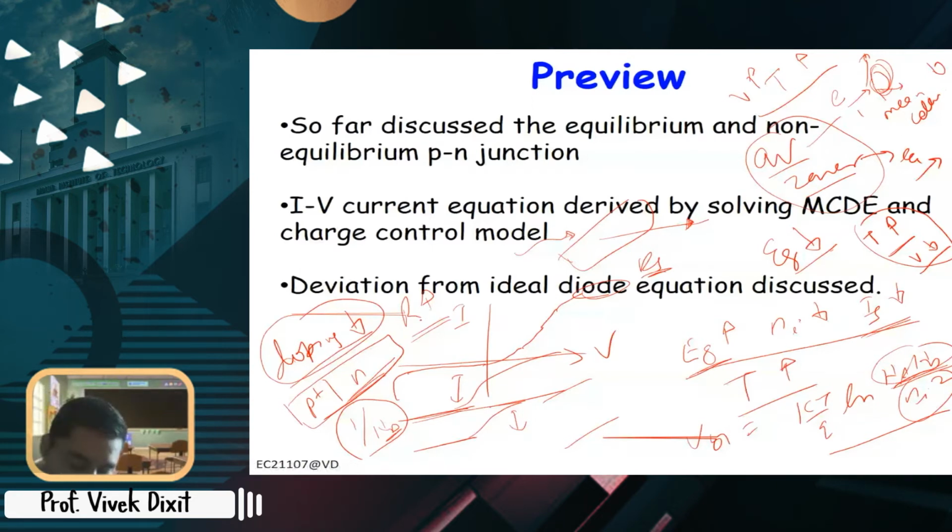So that means if you want high breakdown voltage, you have to reduce the doping, and if you reduce the doping, your resistance will increase, and heating will increase, right? So if your heating is increasing, what will you do now? What other parameter? You can make a large area and smaller length to reduce the resistance. Once you know the conductivity, because this doping will decide the conductivity, then resistance is rho L by A, right? So you can increase the area and reduce the length.